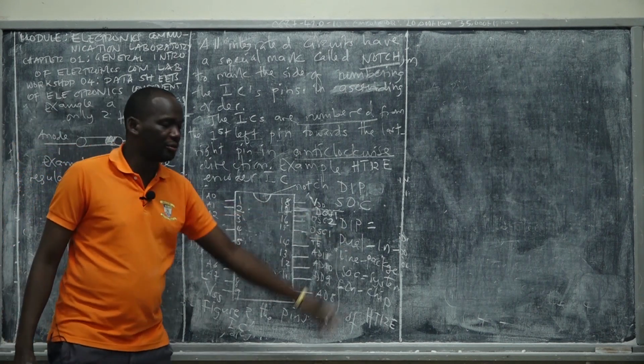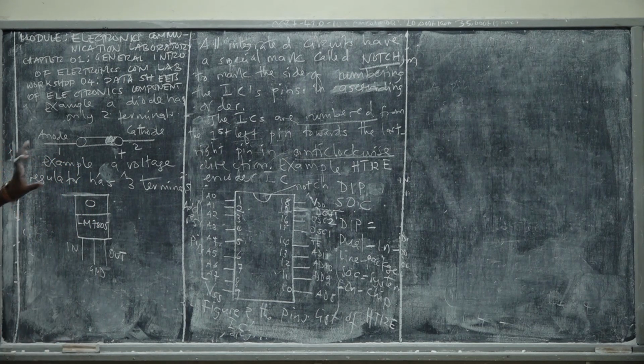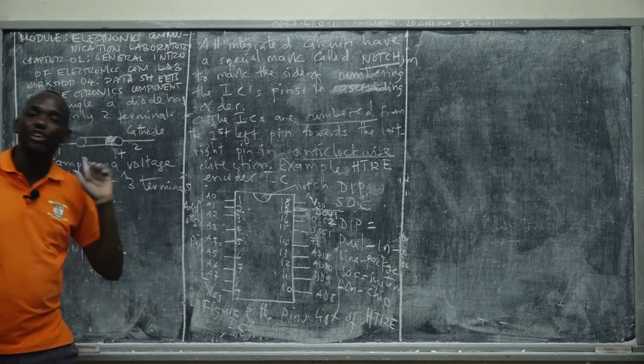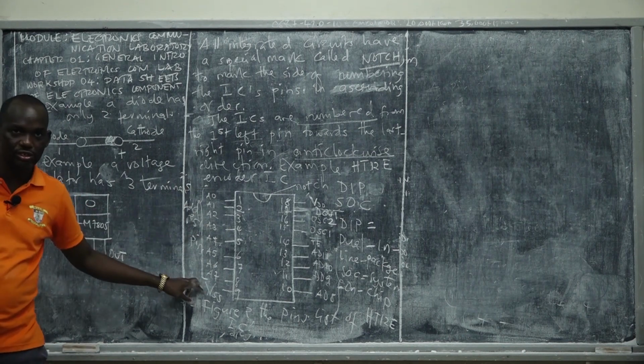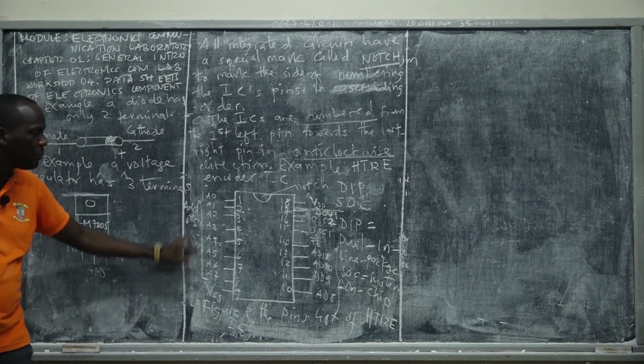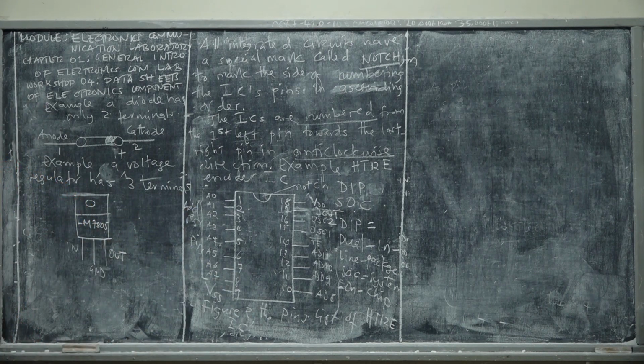Then VDD, we have already discussed the pin number 18. So remember that this part also explains the function of each pin. Say function of each pin. So these pins, they receive address, or they need the address. This address that will be provided to the encoder, you have to provide the same address to the decoder. Otherwise, the decoder will not decode the information encoded by that IC. Are we together? It's just like if you send a letter, if it reaches the wrong destination, then the receiver should not open the letter. He or she has to return it to the post address.